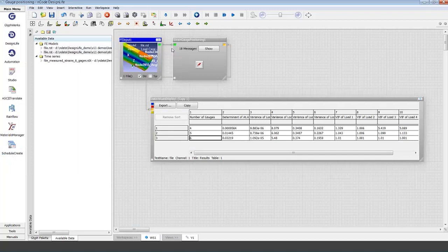Step 2, go record that strain gauge data. That's not trivial, but fortunately HBM provides all kinds of cool hardware for that step in the process. They produce all kinds of strain gauges, data acquisition devices, and so on. So let's say the test engineers go out and measure all that strain gauge data. So step 2 is done, and now we're going to progress on to step 3, which was how can we estimate the loads from those gauge locations' measured strains?